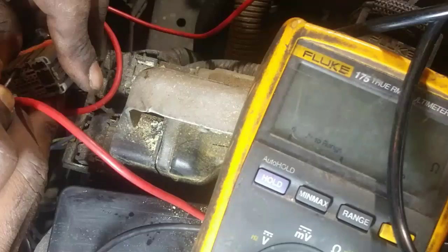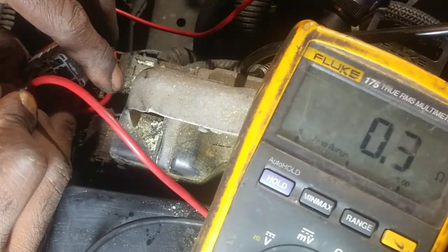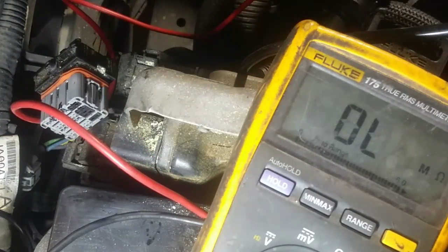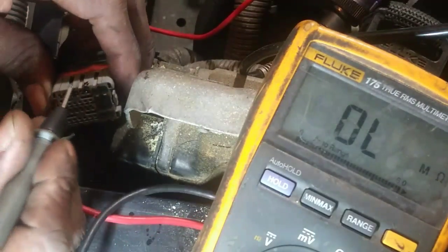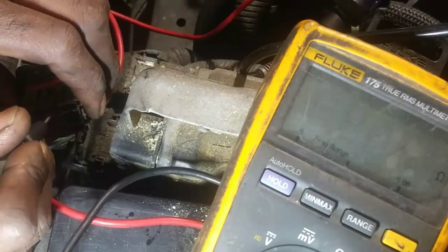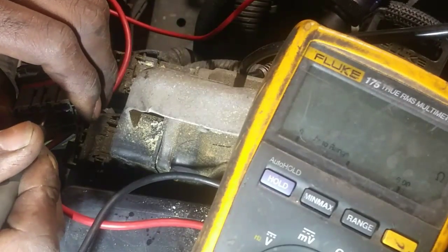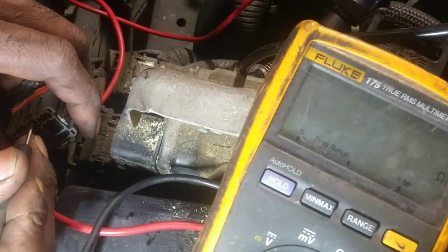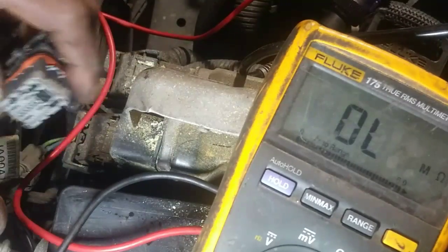Okay, so I'm on the functioning one, so this is the working one. We have 3 ohms. Move to the defective one. Should also have 3 ohms. This is the double mark one here. 5 ohms. Hold on. Wait a minute. 5 ohms. Make sure it's got a good connection. It's not that much. Okay, so we're back at 3. So I just didn't have it connected good. So they're producing the same value.